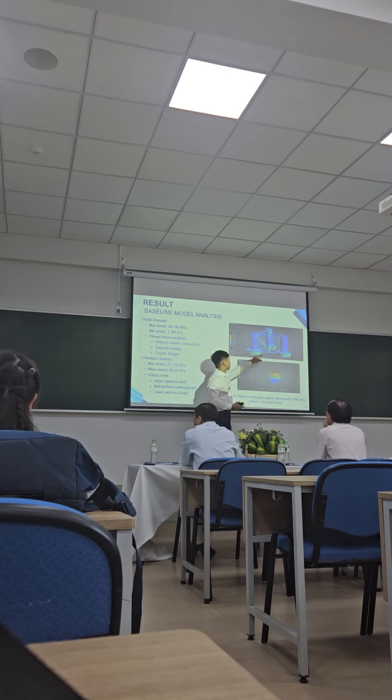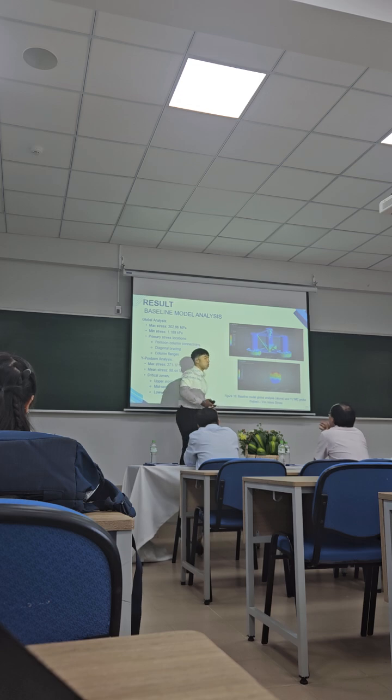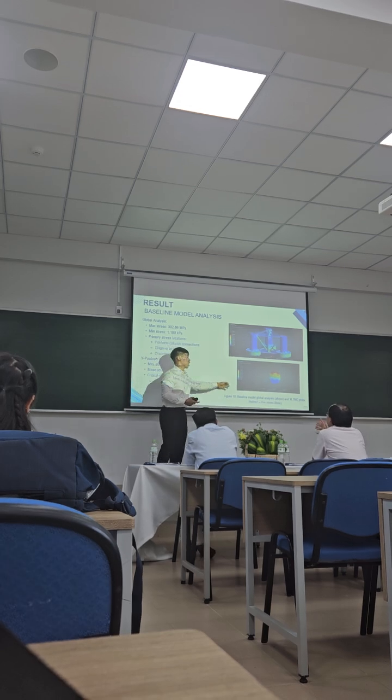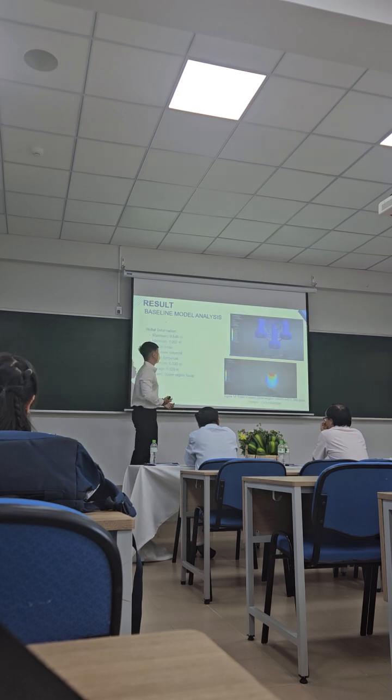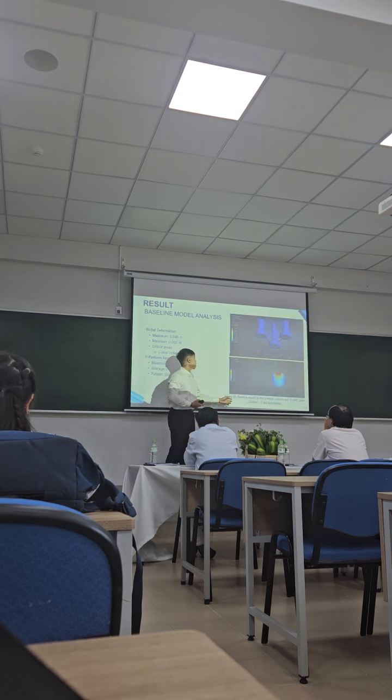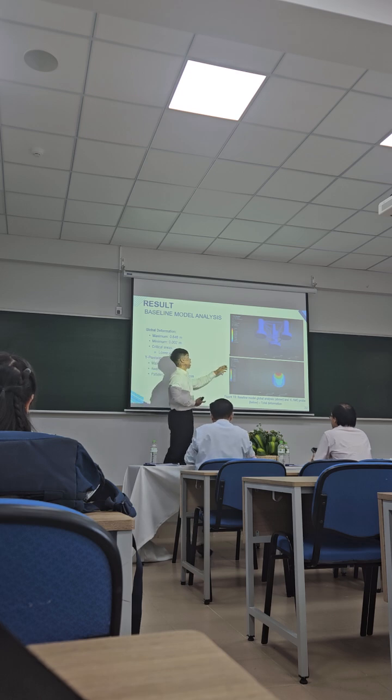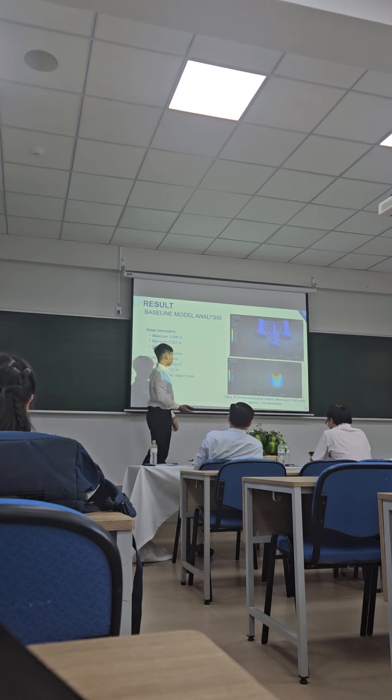And you can see that the highest stress occurs at the YLNC connection. This is the main reason for us to choose this connection behavior as our output for the machine learning model training. In the total deformation in figure 19, we can see the symmetrical pattern of deformation at the bottom column center. The reason for this is the absence of ballast water in that region.